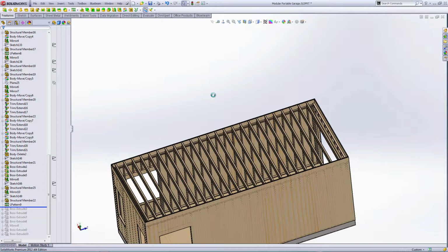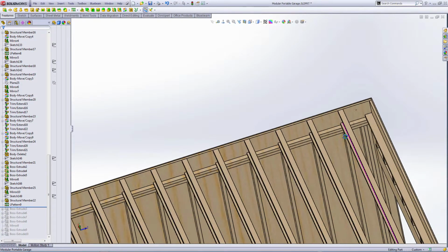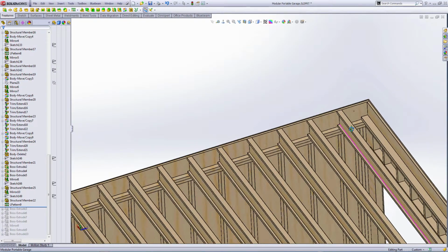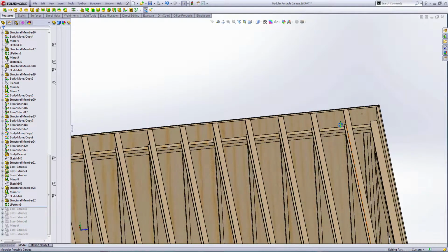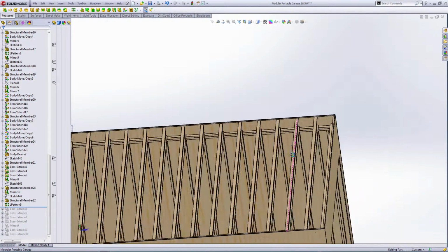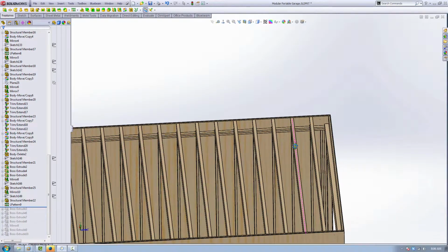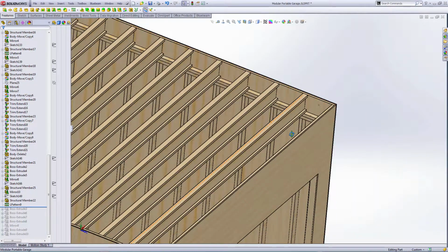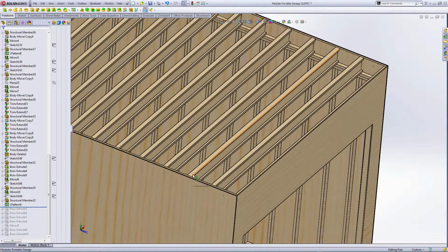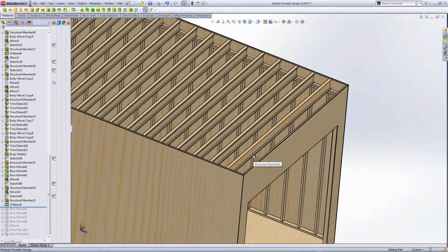And the BCIs should line up with the studs, and you can see that they do. The roof BCIs, floor BCIs, and wall studs should all line up. That way, if you find a wall stud, you know there's also a floor joist and a roof ceiling joist above you. In the past, I've had engineers require blocking in the first two bays. I'm not going to stick them in for the purposes of time. Probably will add them later though. They do help with shear.